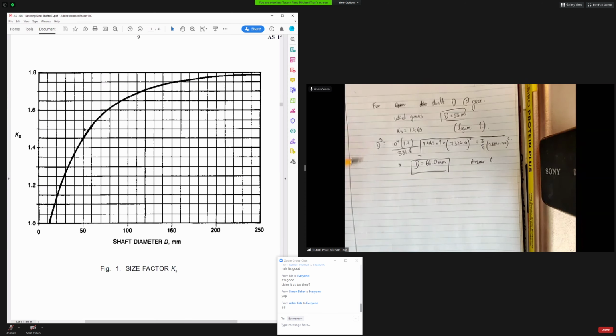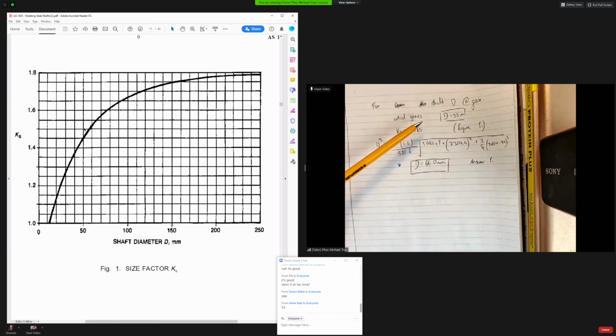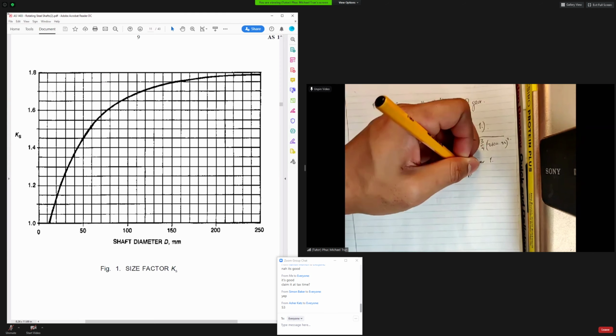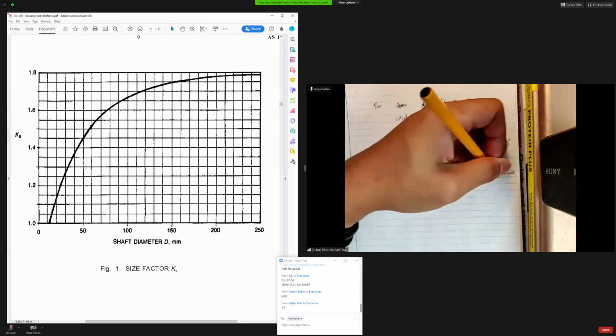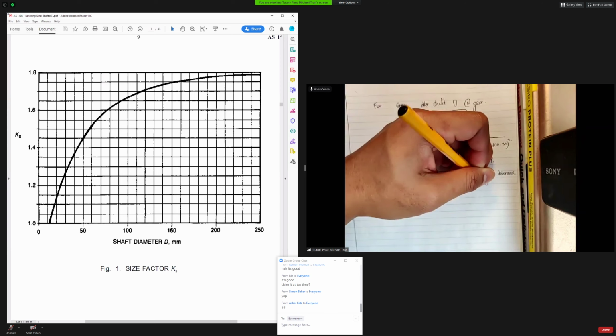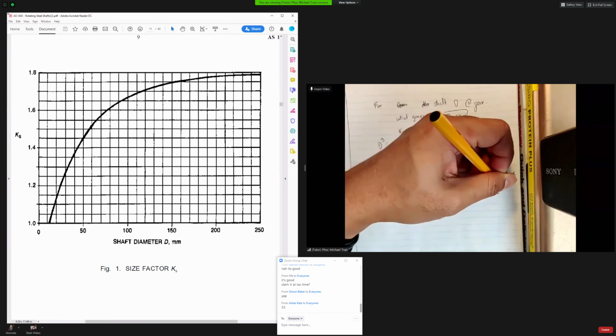All right. From this step, we have to compare our calculation to our initial guess. And what we want is a minimum of, let's say, 1 to 2%. Let's go 1% variance between these two. Because that's heaps, we have to reuse 66 as our guess and find another guess value, shove it into the formula, and get another D. So not within tolerance, therefore retry using D equals 66 as guess.